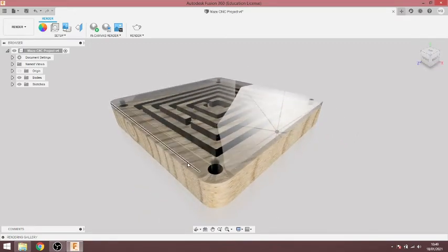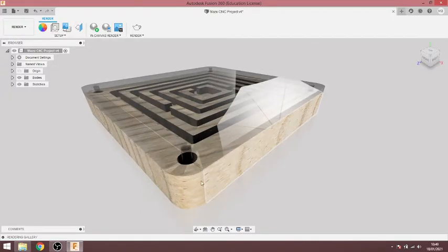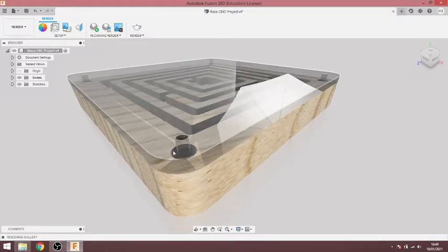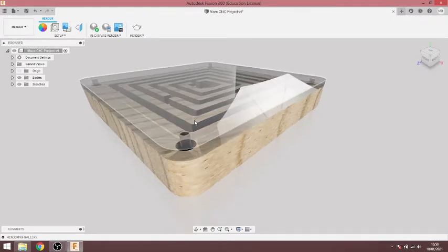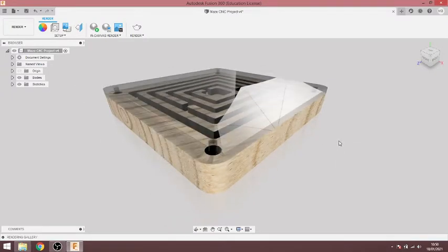And the idea of this design is you just have a small steel bearing inside that follows the maze pattern, and then in each corner the holes within the base, the larger ones, would have a threaded insert tapped into them, and then the acrylic would be fixed using M4 socket head machine screws, probably in some sort of stainless steel or a black coated finish.